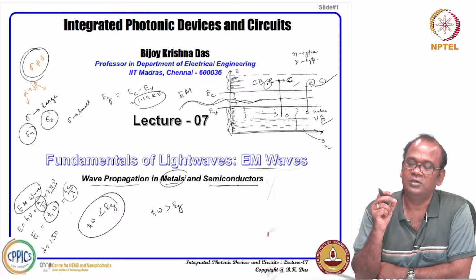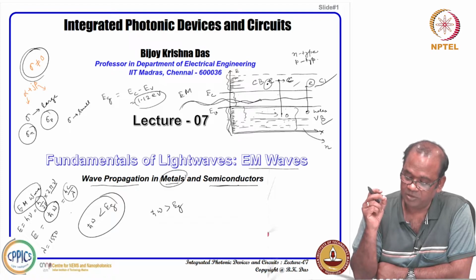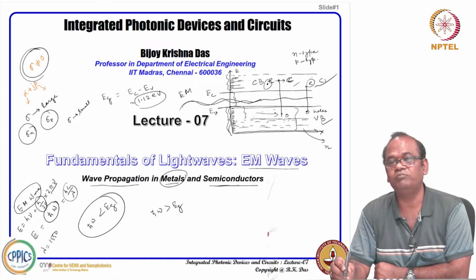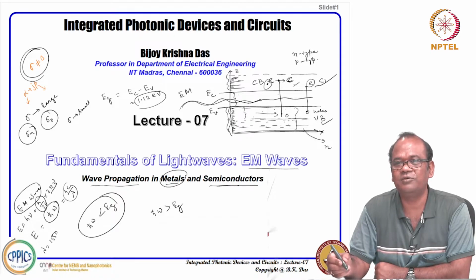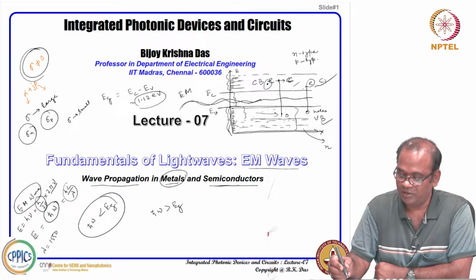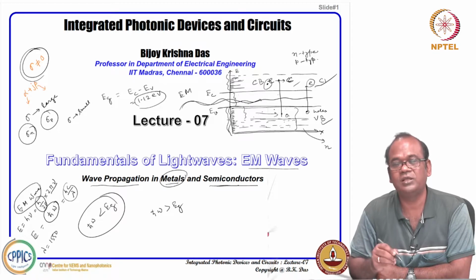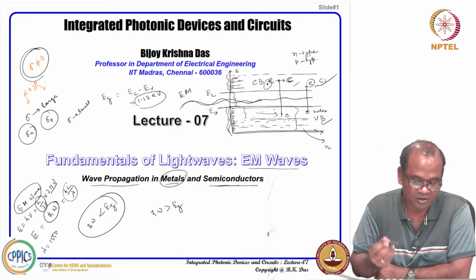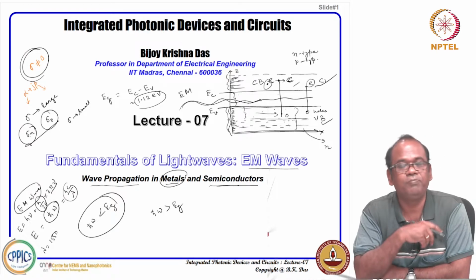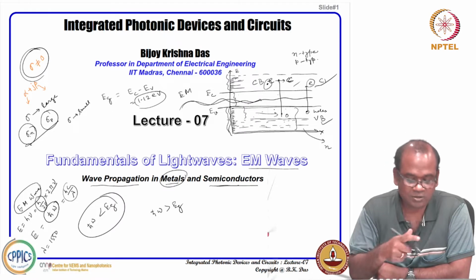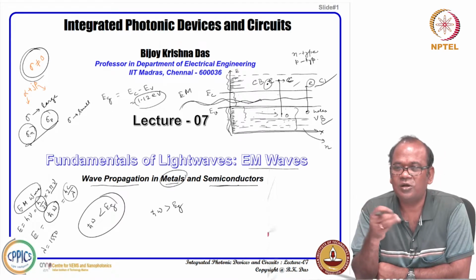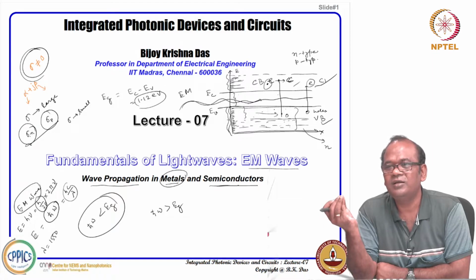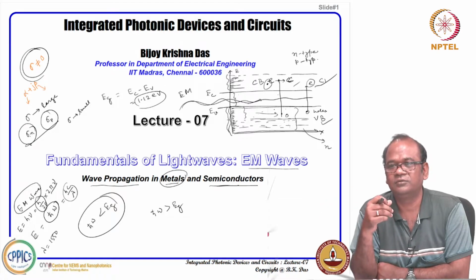But you also have to consider that there are some electrons in the conduction band and some holes in the valence band because of thermal excitation, etc. They can contribute some kind of conductivity. So, you can consider it is not a completely lossless dielectric, it is a kind of lossy dielectric material medium. Okay.